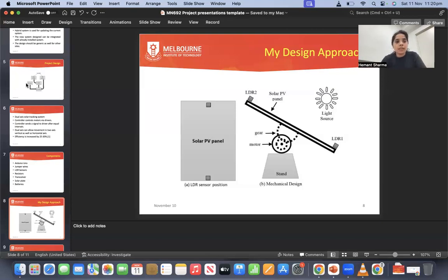With the move command from the controller, the motor will rotate the gear placed within the frame, and the frame on which the solar panel is placed. Gears help in moving heavy objects with a small force. It can be said that the gear can increase the torque and reduce the speed or vice versa. In this scenario, speed is not necessary.